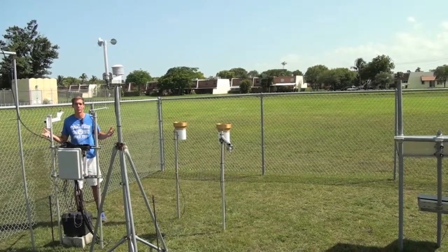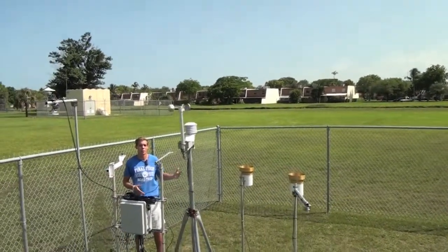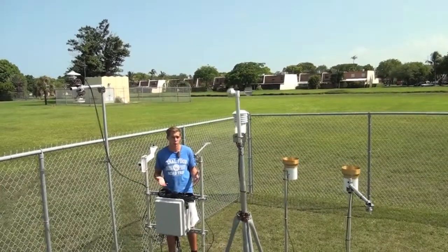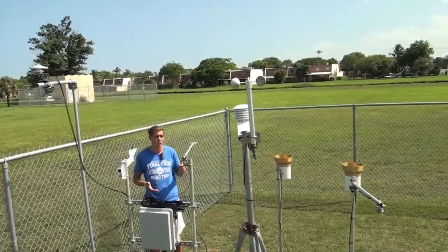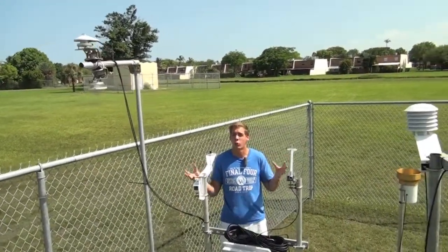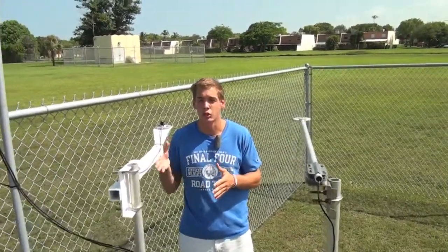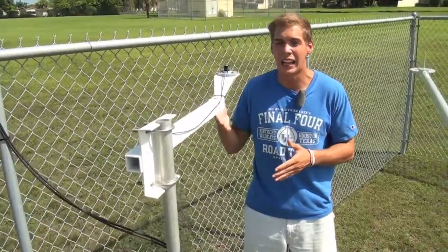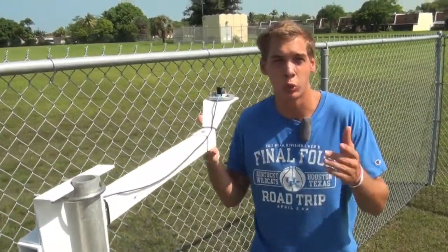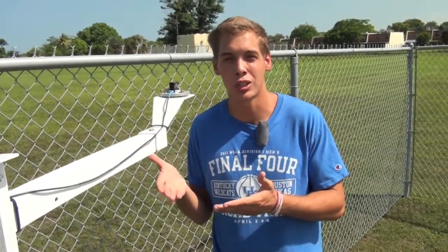Now let me put this in simpler terms. Out of all this instrumentation here at Snapper Creek, its sole purpose is to estimate evapotranspiration, whether it be a tensiometer, a rain bucket, a radiometer, or a temperature probe. They have one job, and it's to estimate ET. But through this estimation equation, as a sole function of PAR, we can accurately estimate eddy covariance ET through one instrument, and that's the pyranometer, the holy grail of ET estimation.